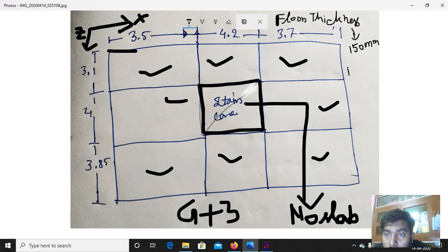The floor load that we have to create, I have told you in the last class, is floor load equals density of the concrete, that is 25 kilonewton per meter cube for RCC, into 0.15. Okay, this is the value of the total floor load. What value will be coming?